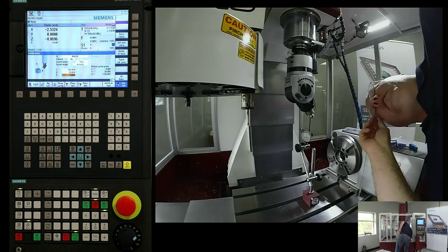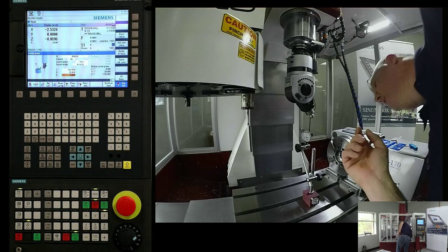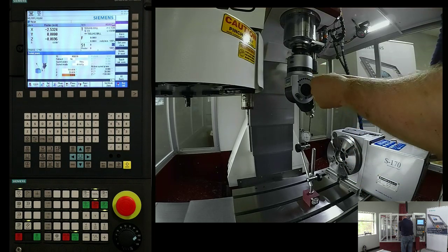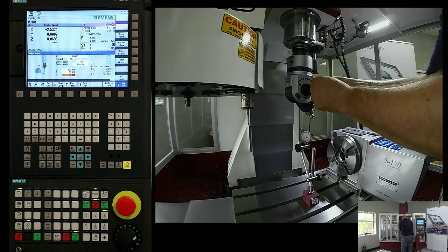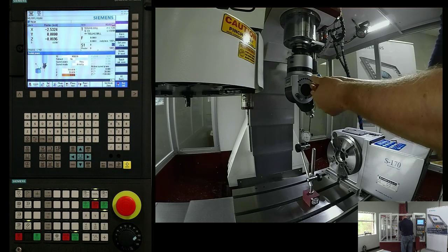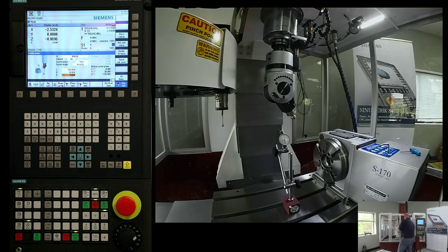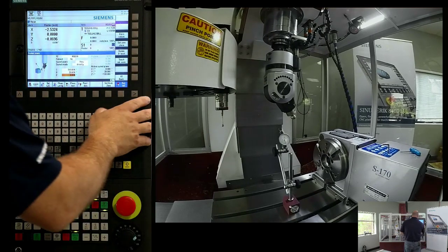There's a scale here on the bottom. Let's try to bring in the 0. See if I'm close enough. And if you're not, when you start just turning this in, it will get tight really quick. It should be nice and free until the bottom. You don't have to crank on this thing. Okay, so we're sitting there, and let's get you a little closer. We're sitting here at 30 degrees.